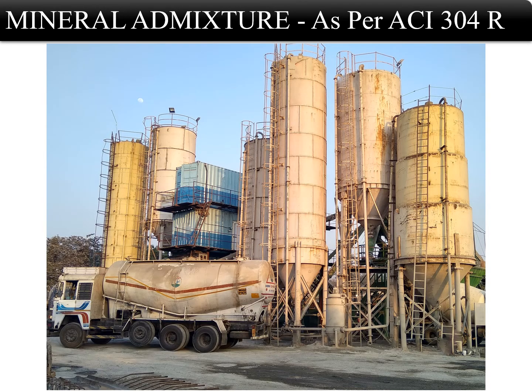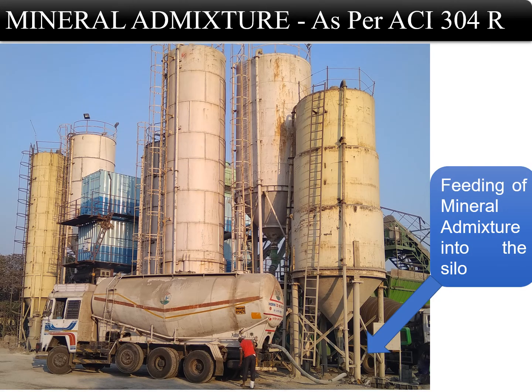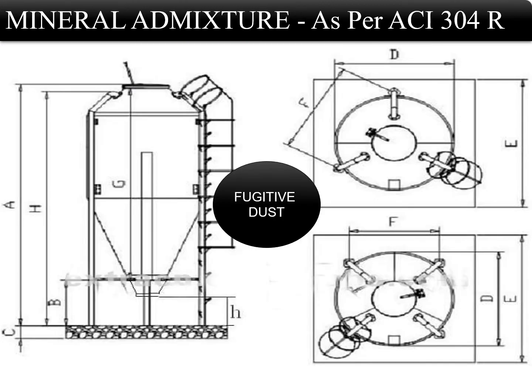Each bin compartment from which mineral admixtures are batched should include a separate gate, screw conveyor, air slide, rotary feeder, or other conveyance that effectively allows both constant flow and precise cutoff to obtain accurate batching of mineral admixtures. Make sure mineral admixtures are transferred to the correct silos by closely monitoring procedures and equipment. Fugitive dust should be controlled during loading and transferring.